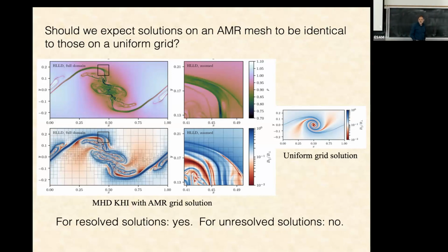So bottom line is, again, the instability is real. This is not a wrong solution. It's just that the initial value problem posed is different in these two cases. One has additional perturbations, which are hard to characterize because they come from the mesh. And this one doesn't have those perturbations. And so the outcome of the solution is different.